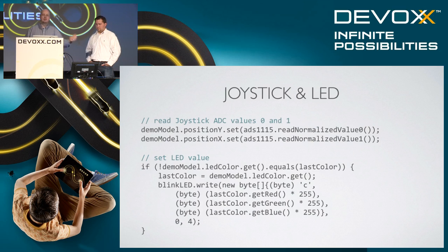So fully left or fully right isn't necessarily absolutely 0 volts or absolutely 3.3 volts, and the electricity coming out of the plug socket isn't exactly right. So there's little bits of variance in there, and so I'm doing a little bit of cleaning up here to turn it into a nice 0 to 1 value that makes it nice and easy to deal with in my code.